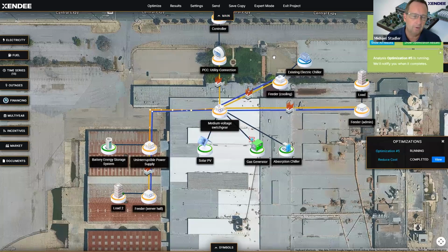And as Rita was showing, you can also adapt where the lines are so that they can go around buildings. If you want accurate losses and you have a lot of power going through the system, it might be good to have accurate locations. But at the same time, don't forget, this is the last step in an economic analysis and the first step in a power flow analysis. And you might go into a one line diagram anyway to do a more detailed analysis. But maybe Rita, you have more to add to this.